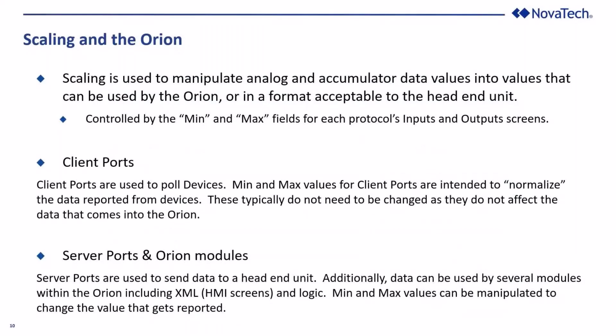Along with server ports going to your SCADA master, you're also sending these input points from IEDs to other modules within NCD, such as Logic or your HMI screens. So the scaling can be performed either on a server port to a master or on a server port to another module within NCD. Go ahead, Brett.